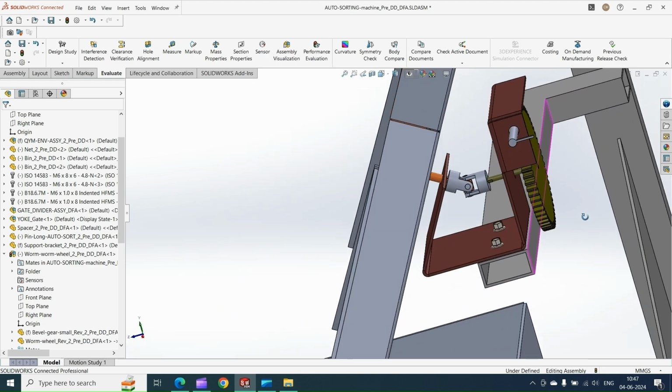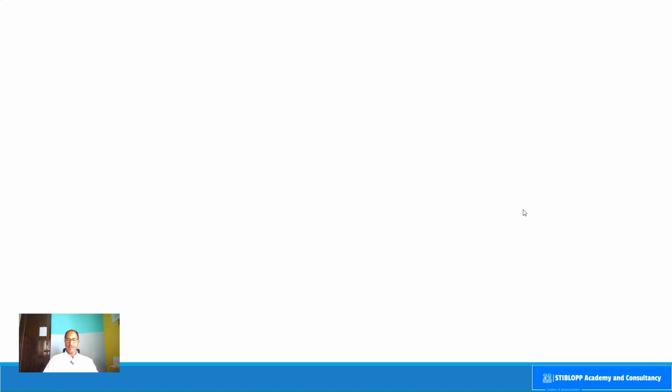Okay. Moving on, the next step that we have in our preliminary design and development process is the mock-up analysis. What is mock-up analysis? Mock-up analysis is a study to find the clashes, clearances, and other detections within the system or between the systems. Additionally, the team also gives us the analysis reports of the mock-up done for our particular assembly, so that the product development team can incorporate them into their design and remove all the clashes or the issues.